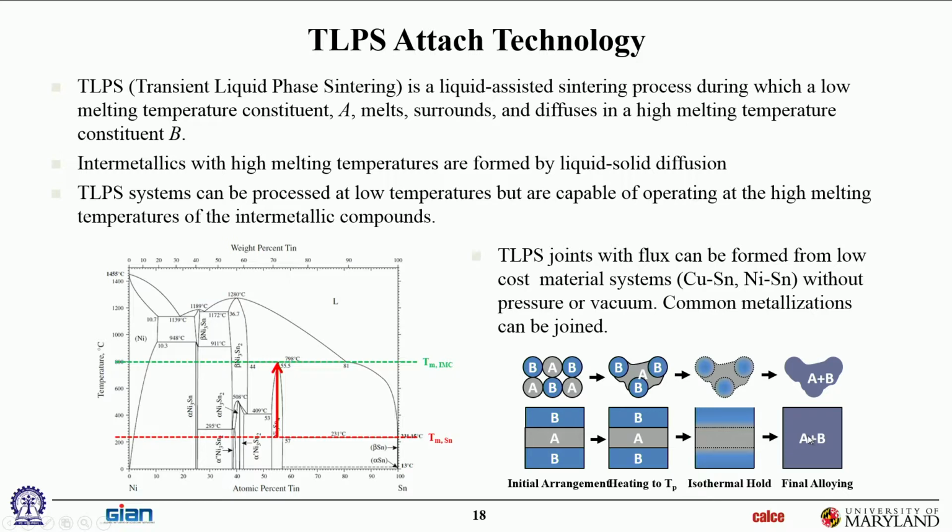There are some issues with it. Well, the advantages, you've got excellent for very high temperature applications. The disadvantages are more on the mechanical side. Intermetallics, as you know, are very stiff, very strong, very brittle. So think about if you make a die-attached material out of this. Now you've got a very unyielding, stiff, strong material under the die. All the thermal expansion mismatches are going into the chip.